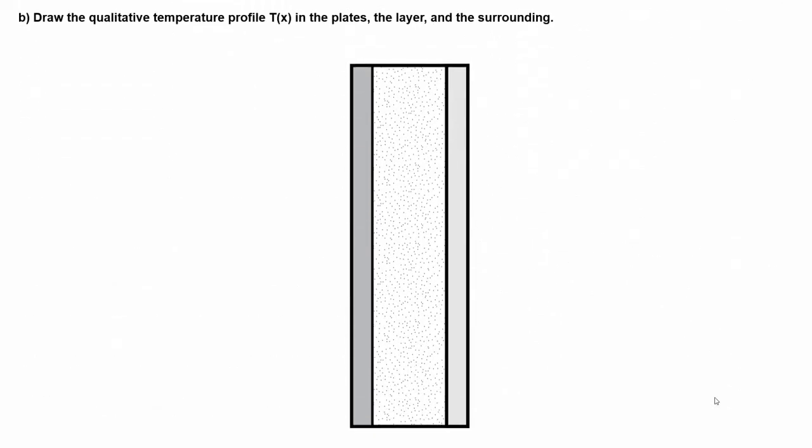In the second question, we are asked to draw the temperature profile for all plates and its surrounding. We know that all temperatures will lie in the range of Tmax and Ta. Far enough away from the plates, the ambient will equal the temperature Ta. The upper plate surface is equal to Tmax, and when moving from the left to the right, the temperatures at the interfaces will decrease. We don't know the exact temperature drops, but since the upper plate has the highest conductivity and the lower plate the smallest, it makes sense that the drop will increase per layer.